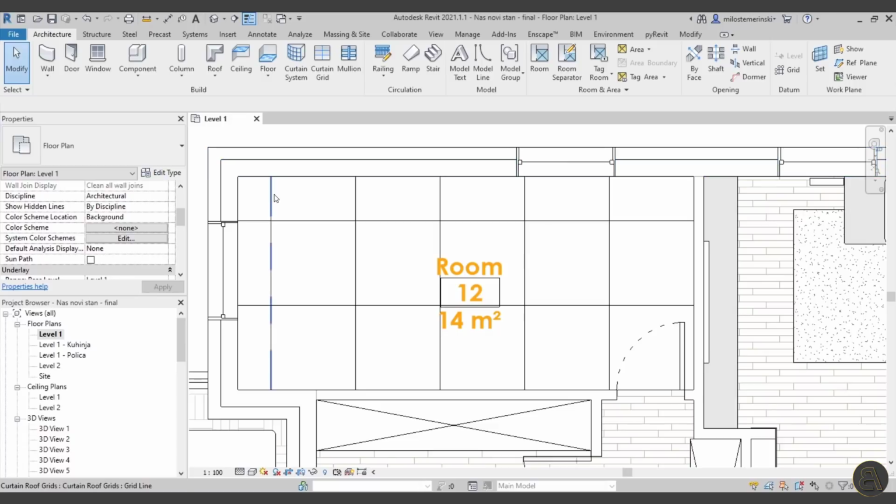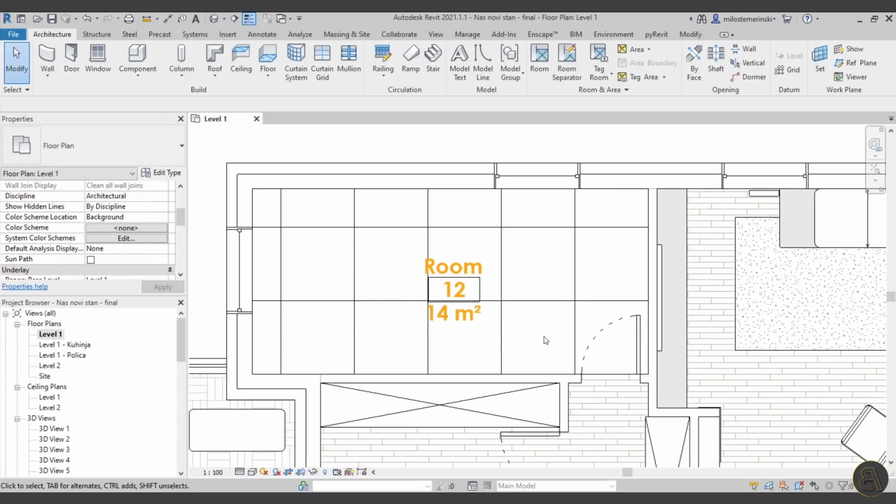So this is a little bit more than half a panel, but if I measure from here to here, it's going to be 39. So this is a lot less than half a panel. So judging from this, we only need 1, 2, 3, 4, 5, 6, 7, 8, 9, 10, 11, 12, 13, 14, 15, and then from the remaining material, we can place these 3 smaller panels here, because we can use some of the little excess material that's left off from these when we cut these.